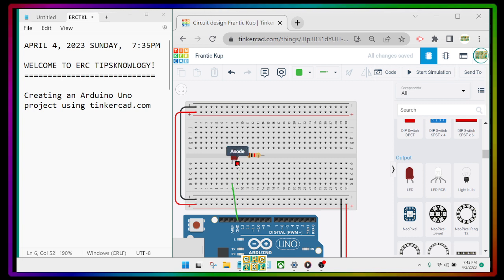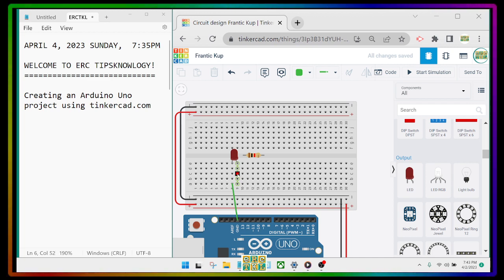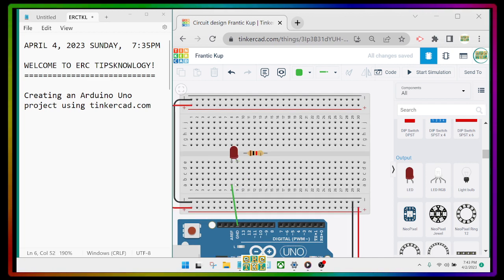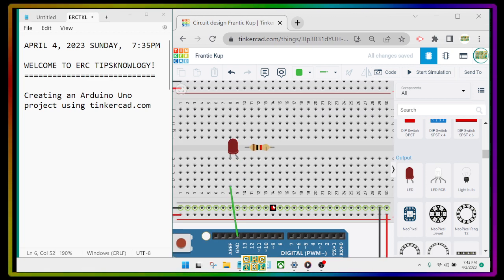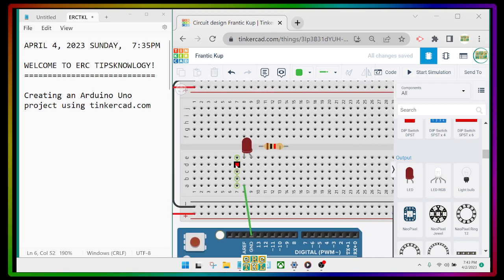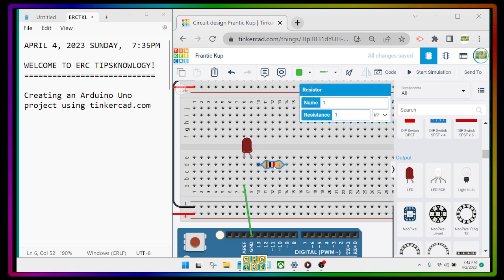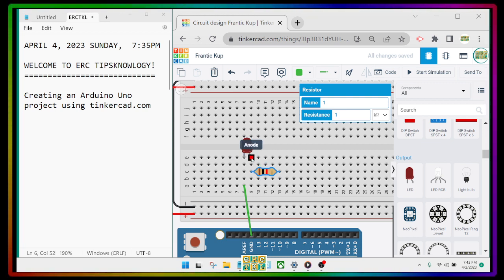Now, the other end of the resistor may be connected on letter E number 9, where the anode is connected. So we can use D9, C9, B9, or A9. So what I'll do is I'll choose, for example, C9 to connect terminal 1 of the resistor, and it's connected to E9, which is the anode. And then the other end is now on C13.